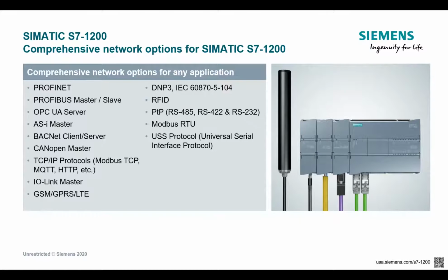This is just reviewing those different options that we had talked about. One thing I didn't mention on the previous slide is MQTT. That's a pretty popular IoT protocol. I have a few customers that have utilized MQTT to push data into AWS or Azure and create custom web pages with a 1200.